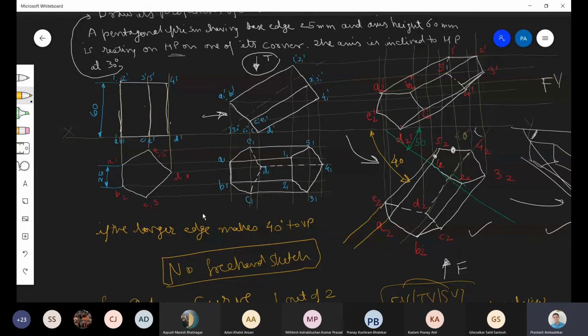So you practice drawing light line. Light line draw करने के लिए use light hand to draw thin line. And for thick line, don't give excessive pressure, but then try it. ज़्यादा थिक करने की कोशिश नहीं करना. And this should be a single stroke line. I am telling it is single stroke. एक ही बार ड्रॉ करना है. उस पर 3-4 बार, देखो यहाँ पे ड्रॉ किया ना 2-3 बार, ऐसे ड्रॉ नहीं करना है. That is not accepted. It should be drawn in one stroke. सिंगल स्ट्रोक में ड्रॉ करना है. Okay, and practice this some because you may not be able to complete